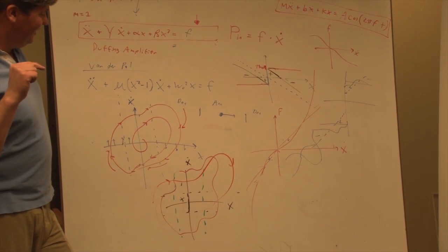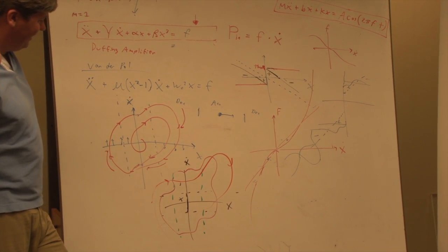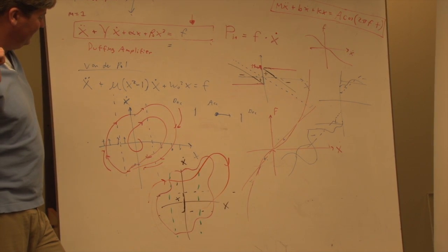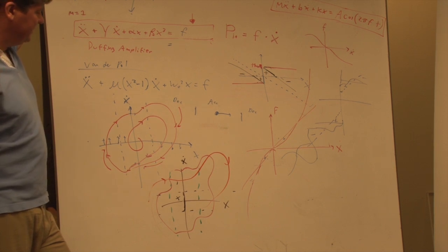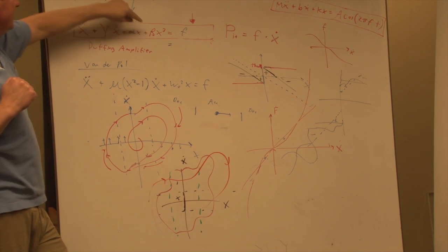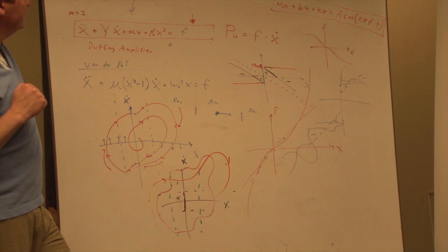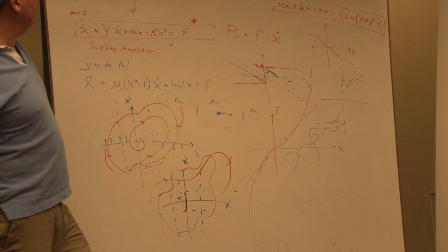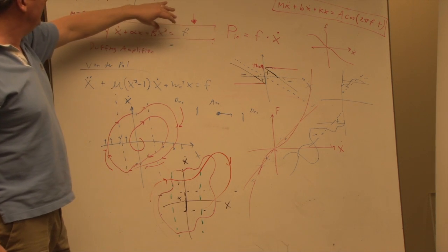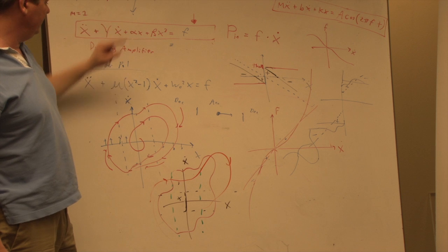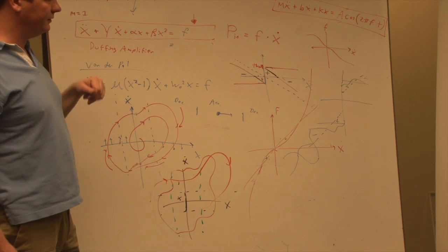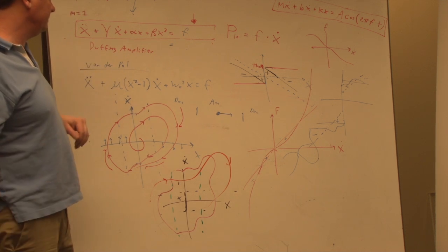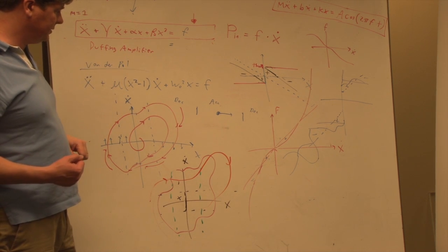So in summary, the main points are that if you want the amplitude to increase as frequency increases, you have to have a stiffening spring in your system, something that looks like a stiffening spring, which is what we want for running. And you can make them oscillate by driving with a cosine as a function of time, but that's not good if you want to stay at resonance, because if you're not perfect, you'll fall off the resonant crest curve. So instead, it's better to try some sort of phase driving, and by phase driving, we mean just do positive work when possible.